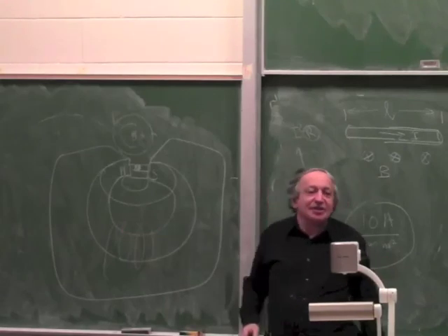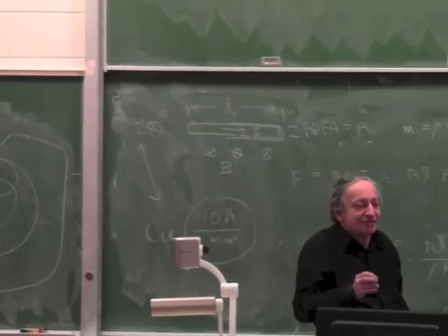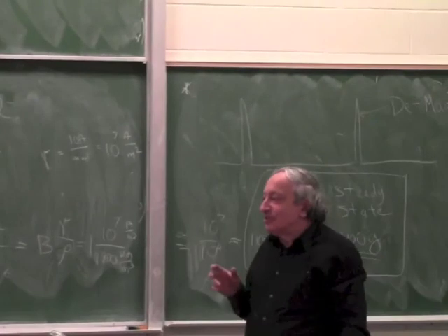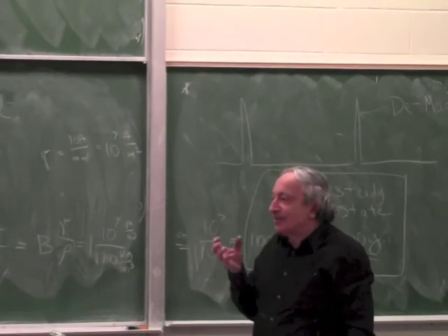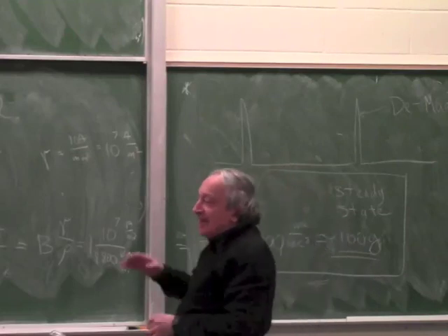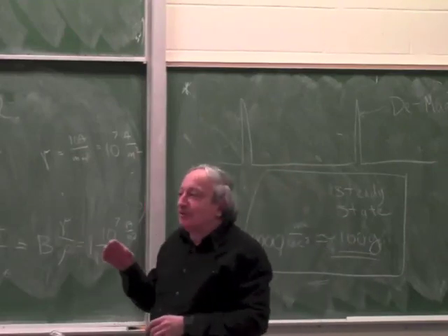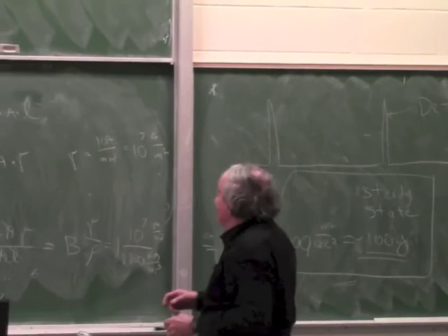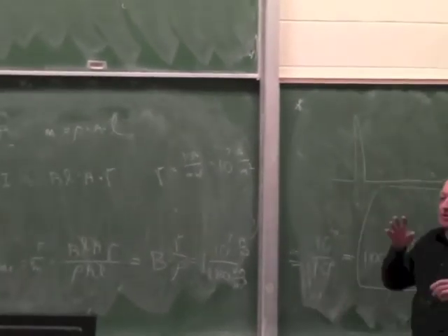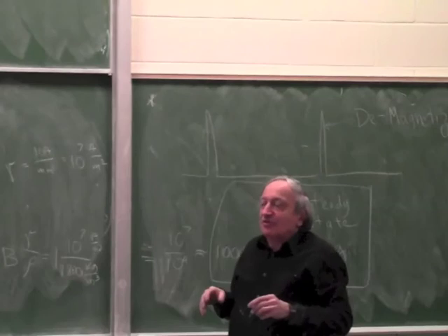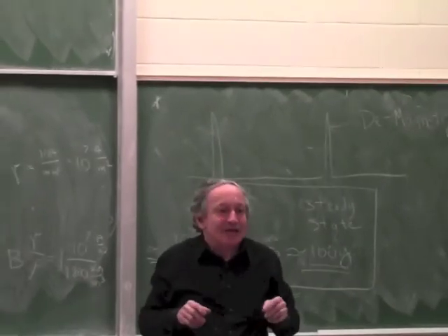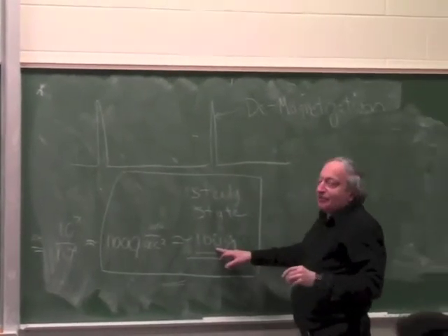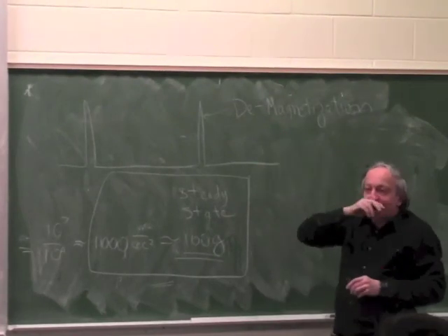Okay? And that's why you see on actuators which have to move fast with pulses, sometimes you see a huge magnet. Okay? For example, loudspeakers. Loudspeakers have fairly strong magnet and fairly big magnet because their average current is low, but from time to time you get some pulse in the music. When somebody hits the drums, the loudspeaker has to jump. You need a very big current, so you want to make sure it doesn't demagnetize it. So for moving coil actuators, which have to work beyond that number for a pulse, you have to make sure you don't demagnetize. Basically means big magnet.